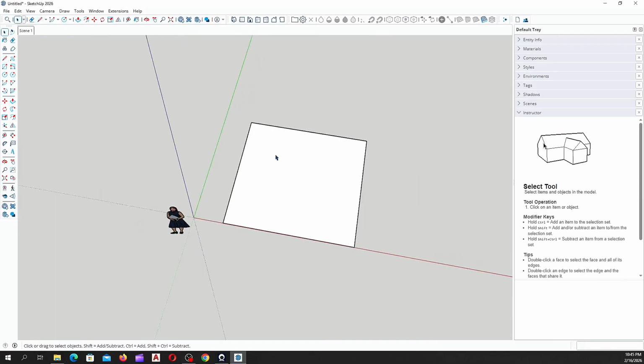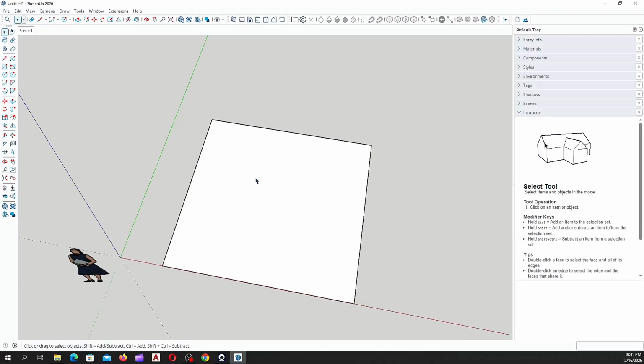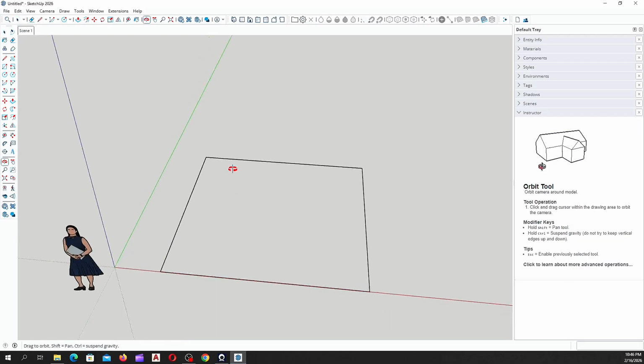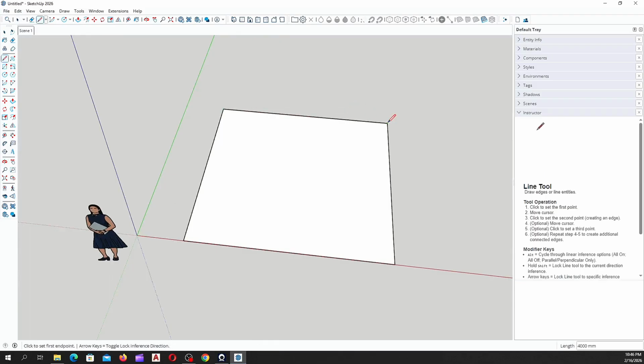So you see our SketchUp, we have what we call edges and faces. Whenever we have three or more edges, it produces a face. So all of these lines are called edges. Okay, these are the edges. So bringing three or more edges together, it produces a face. So this face is independent from the edges. I can delete this face. You see, our edges still remain, and I can simply bring it back by using our line tool. You see, immediately we have this back.